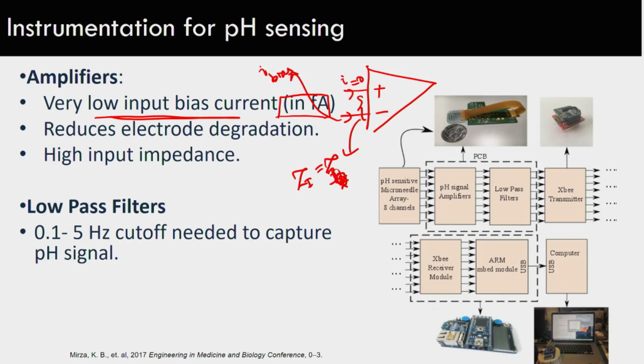So what happens here is with the silver chloride reference electrode. Let's say this is the pH electrode. This is a very simple diagram, I am not doing the detailed one. Here you would have the reference electrode, which is AgCl, and if you have seen the AgCl reference electrode, it is a glass electrode, and there is a salt frit at the bottom.